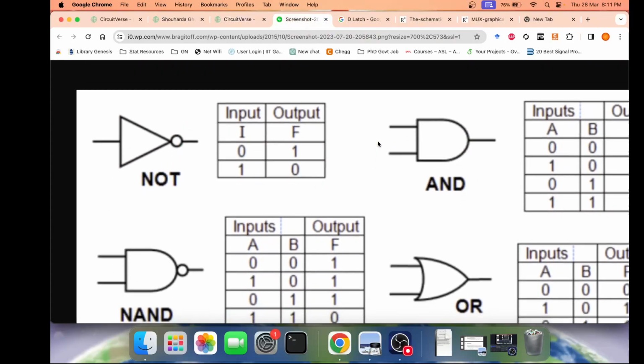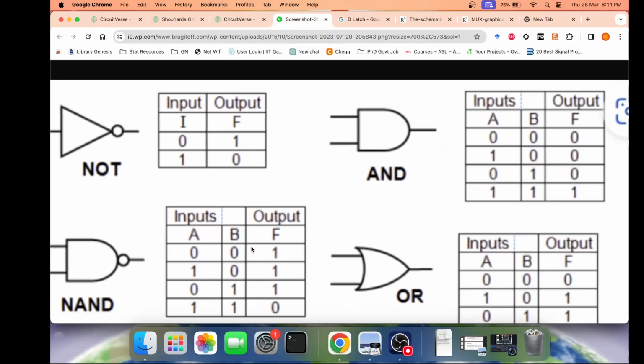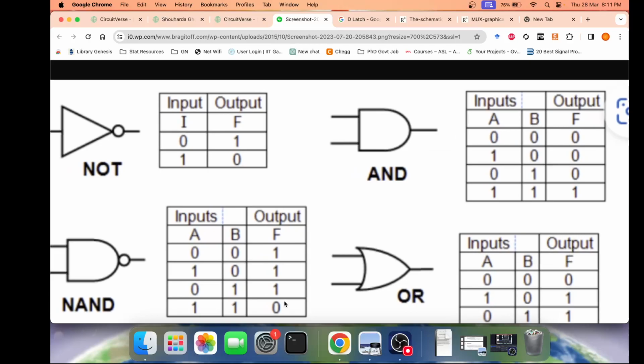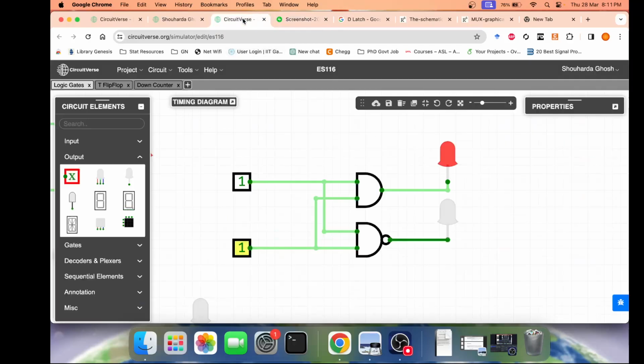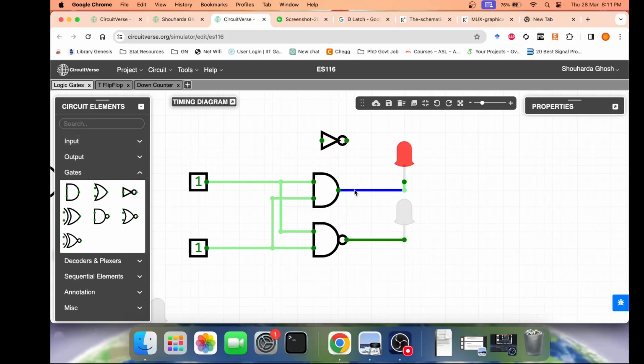And this you can once again verify from the pattern over here. The AND gate gives a 0 0 0 1 pattern, and the NAND gate gives a 1 1 1 0 pattern. So a NAND gate is simply an AND gate in front of which you keep a NOT gate or an inverter. In other words, if I put the NOT gate in front of this AND gate, for all the cases the outputs will match.